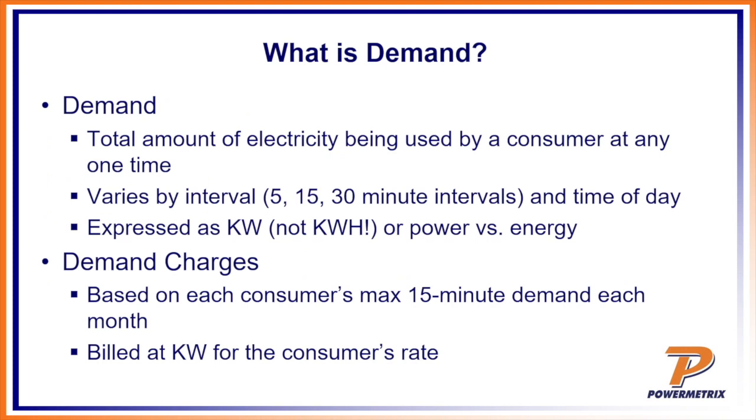So what is demand? Demand is the total amount of electricity being used by a consumer at any one time. Think of it as the amount of work being done in an increment. An interval, most of the time, most utilities break up into a 15-minute interval. As the utility uses that consumption in that 15-minute interval, they measure that and can bill accordingly, right? Exactly.